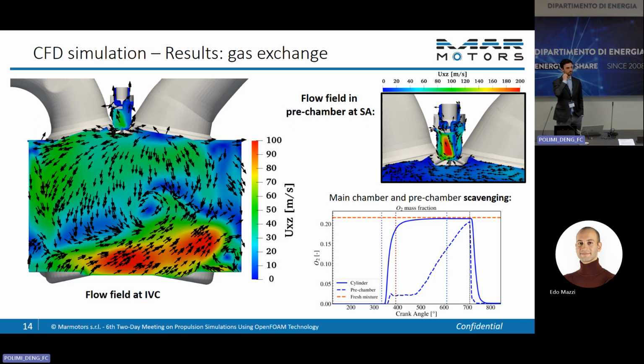You are way thicker than the flamelet regime. Unfortunately, yes. And there is also a recirculated pocket inside the flame. Yes, exactly. That's the thing. Can I answer? Yeah. The model we have here is based on Peter's correlation, which is a little bit wider than the flamelet application. So it treats the triangle regime rather well, it's an ancient but very nice correlation.